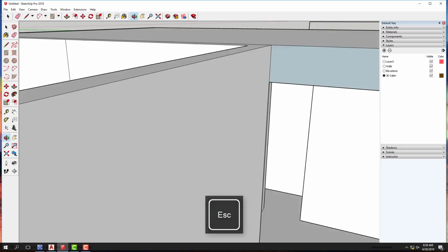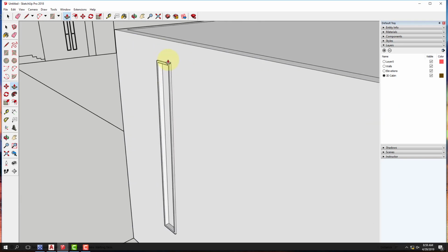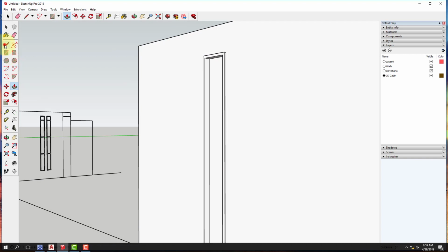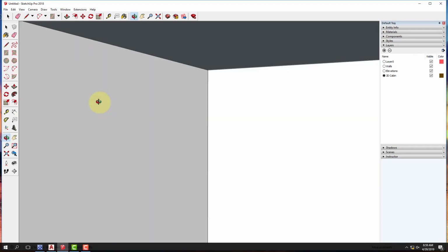Now the window isn't on the inside of my building just yet, because I haven't drawn it through. So in this scenario, I need to be able to draw it through. I could start right here, and I could draw this all the way to wherever it meets the inner face. There it is, on face. I'm just leaving that long there for a second.